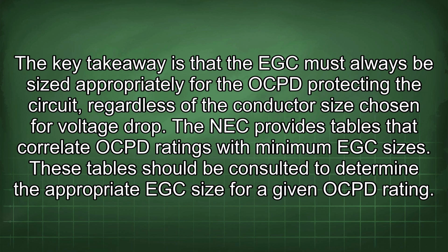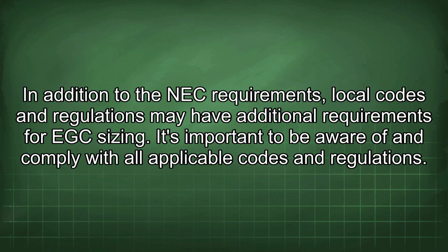The NEC provides tables that correlate OCPD ratings with minimum EGC sizes. These tables should be consulted to determine the appropriate EGC size for a given OCPD rating. In addition to the NEC requirements, local codes and regulations may have additional requirements for EGC sizing. It's important to be aware of and comply with all applicable codes and regulations.